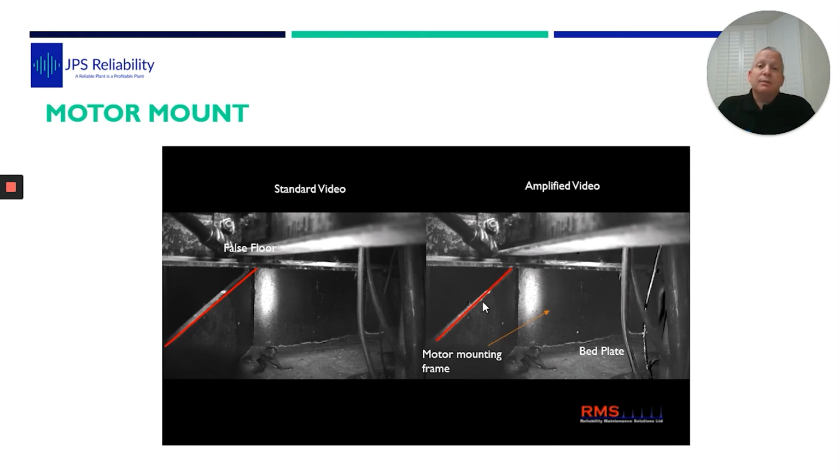So then we had to work out, well, how do we stop these motors failing? The easiest option would be just to speed the motors back up to the highest set point, because they ran fine at that for years and years. That wasn't an option because energy efficiency is stated they had to run lower. Next would be redesign of the pumping station. Put in, instead of a cardan shaft, motor and pump, just put a standalone submersible pump set down below and let that run.